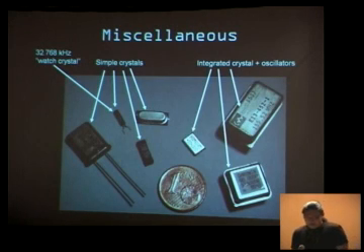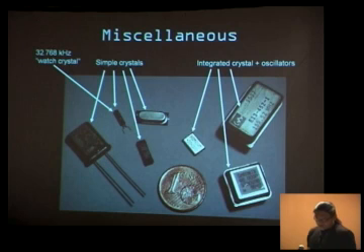Here are some miscellaneous devices. Just some crystals. These are used for time bases for computers and so forth. They have a very wide range of packages, so I want to give you an idea of what to look for. These are the more modern oscillator type packages. These are older CAN style oscillators. These are just simple crystals that don't actually do anything of their own. They're simply a piece of cut quartz with terminals on them.